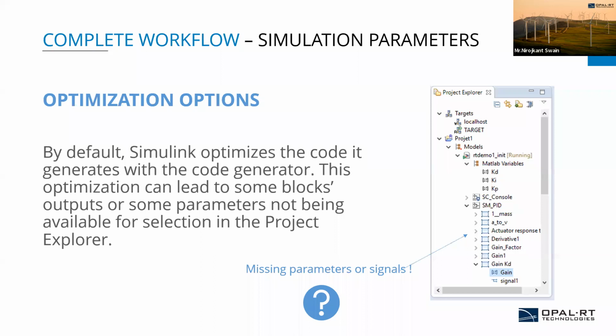Here, one option is your optimization option. Just note down this point. Suppose we are using one sine wave at the time your model is executing, and I want to change this sine wave frequency. How can I change it? No need to reset your model.